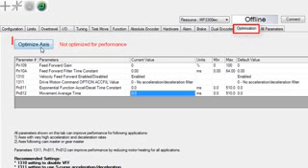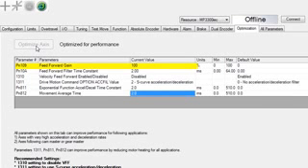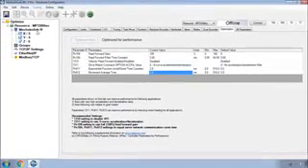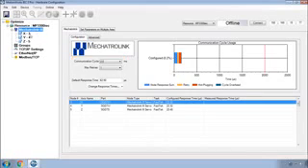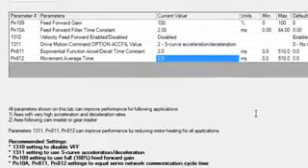When you click the button, Optimize Axis, it sets the feed-forward gain to the maximum of 100%. The time constant is set to match the mechatronic cycle, in this case 2 milliseconds. Velocity feed-forward is disabled, and an S-curve acceleration filter is applied with time constants also set to match the mechatronic cycle. So why bother doing this?